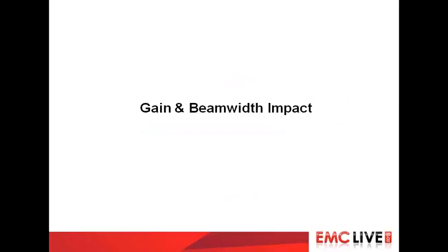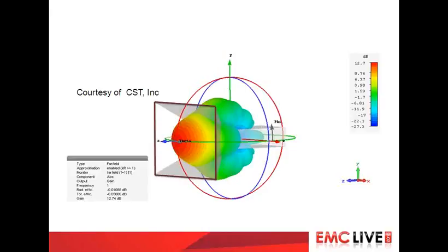So let's look again at the rather rudimentary horn antenna made from flared waveguides. And there we have it. I'll read it for you because I can probably see it better than you. I'm looking at the information on the bottom left, and it says a frequency of 1 gigahertz. Try and remember this: it has a gain at 1 gigahertz, this very rudimentary horn, of 12.74 dB. And we know now that's actually dBi.